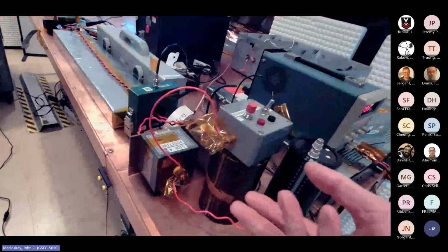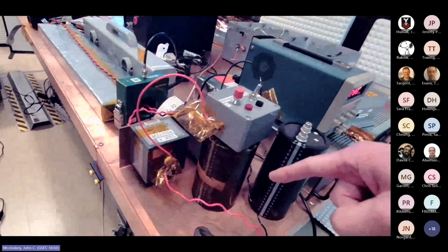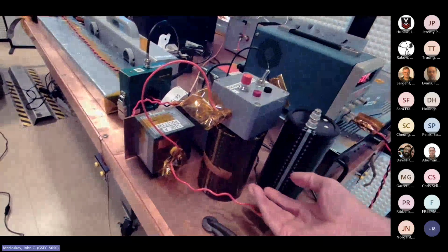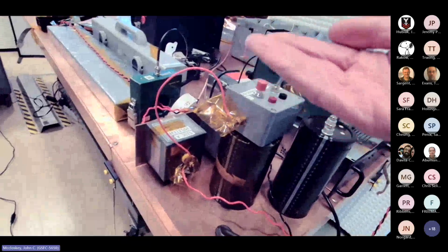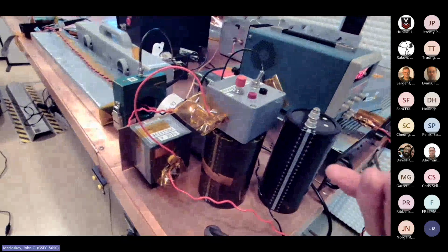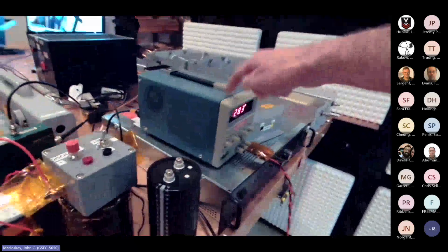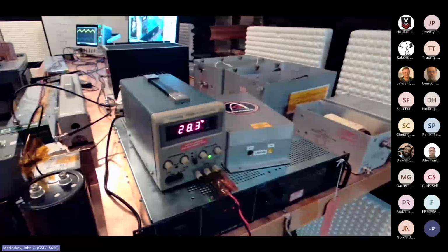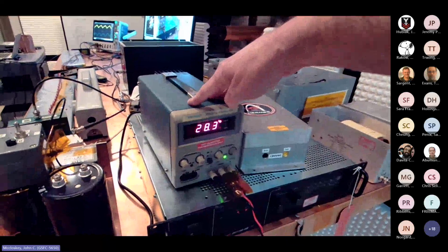You don't want to be limited by the source impedance, and that's one of the major points that I'm going to get across today. So this gives you a low source impedance that can provide whatever current, essentially, that the EUT wants to draw. It also decouples you from your power supply. You can basically use any workhorse power supply. You don't have to specify some ridiculous source impedance for a given configuration.